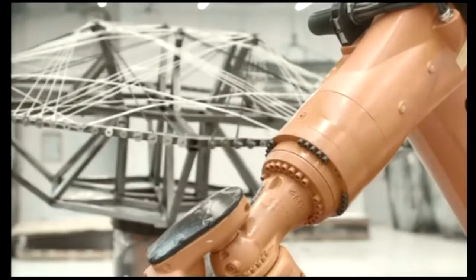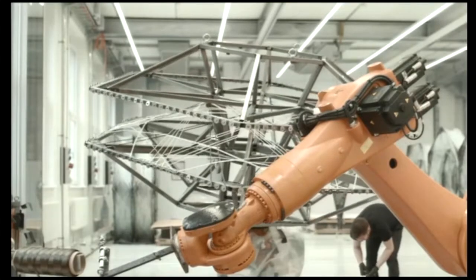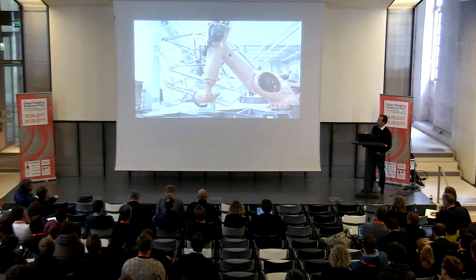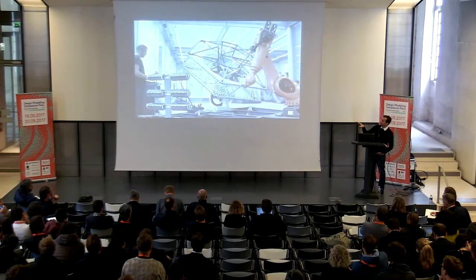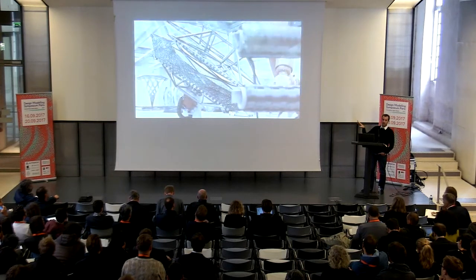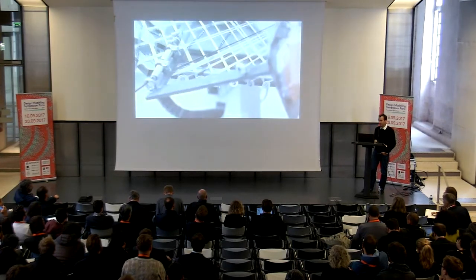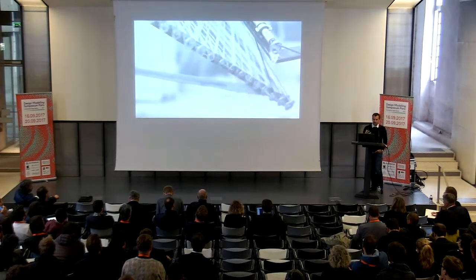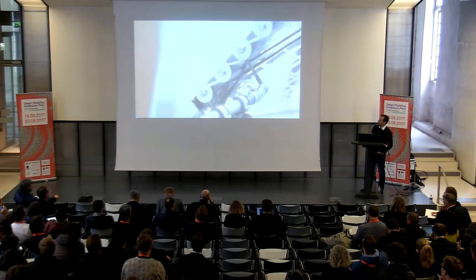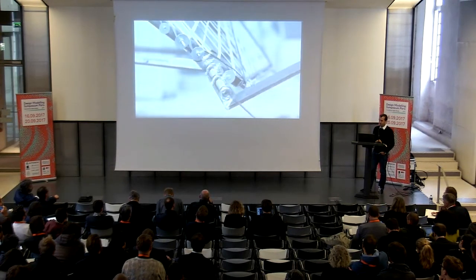So they run through a resin bath, and then they're impregnated with the resin, and in that state, they're applied when they're still flexible and wet onto the framework. And then initially, this hyperparabolic body of glass fiber is built up, and then the carbon fiber is laid onto that embedded mold, so to say, in the way that is actually needed for each single component.